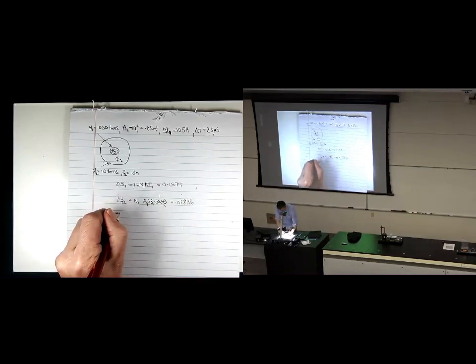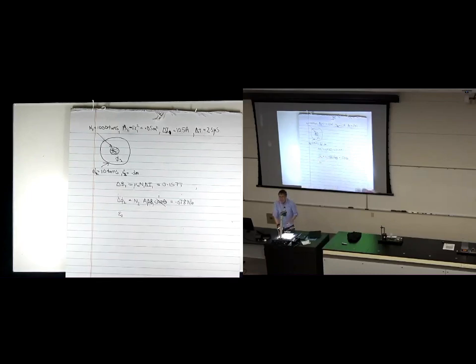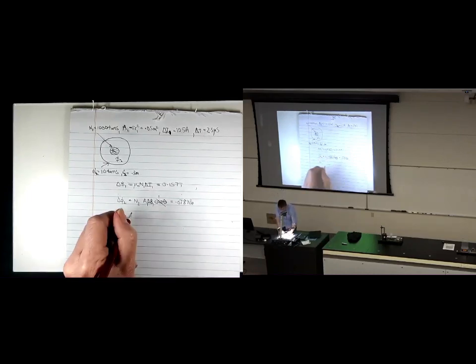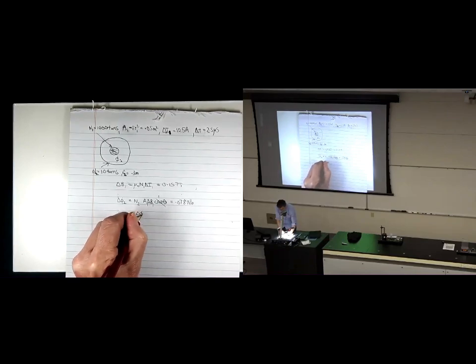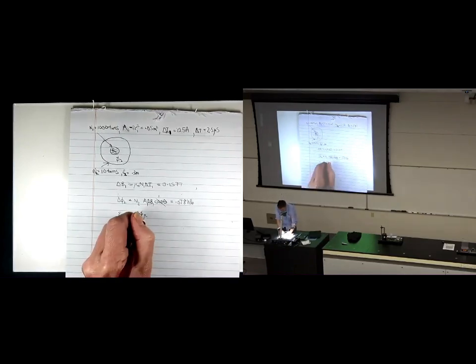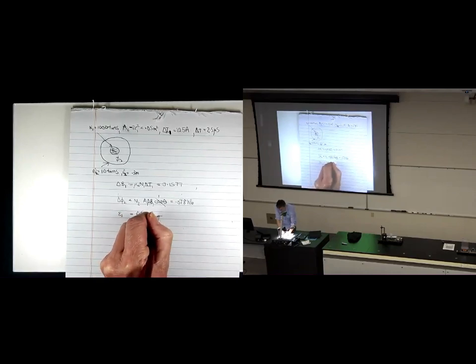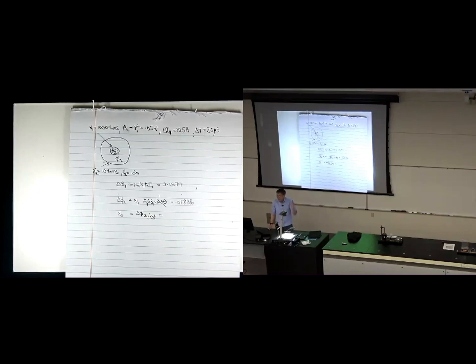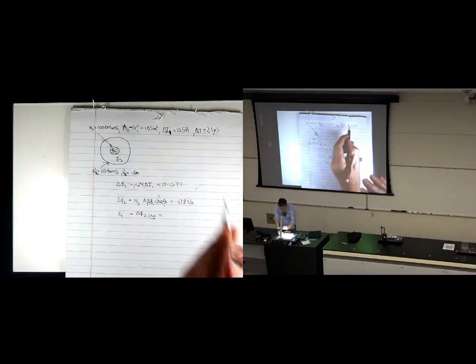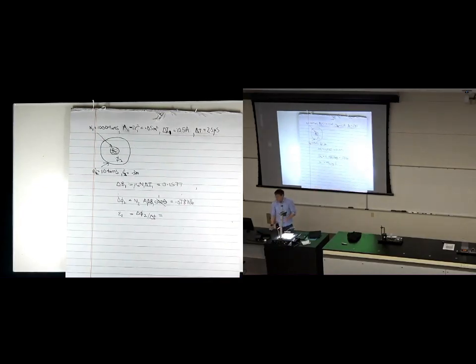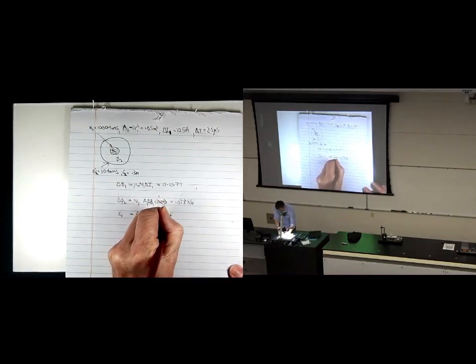Now we're almost there. The EMF induced in the coil, subscript 2, is the change in flux through the coil, delta phi 2, divided by the time interval over which that change occurred. We know both of these. The change in flux is 0.078 Webers. The time interval to switch the circuit on or off was 2.5 microseconds. We were given that information, here it is upstairs. So if I divide 0.078 by 2.5 times 10 to the minus 6 seconds, you get 31 kilovolts.